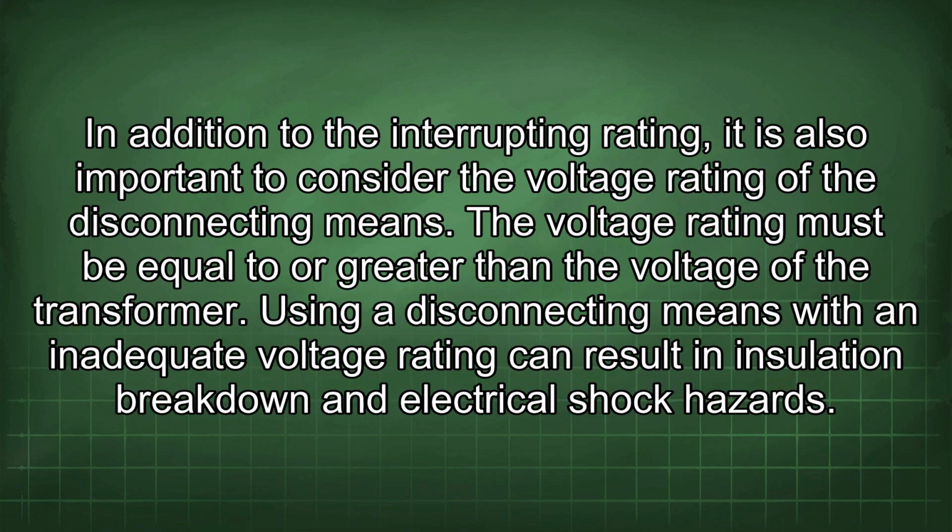In addition to the interrupting rating, it is also important to consider the voltage rating of the disconnecting means. The voltage rating must be equal to or greater than the voltage of the transformer. Using a disconnecting means with an inadequate voltage rating can result in insulation breakdown and electrical shock hazards.